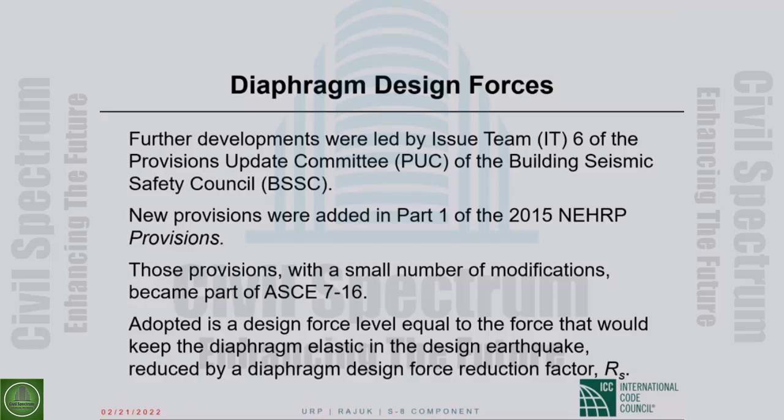Read that one more time. Can we consider slab on grade as a diaphragm if collector elements are inserted between slab on grade and column, but there is no connection between grade beams and slab on grade? Yeah. The answer to the first part is yes. The slab on grade can be a diaphragm if you choose to take lateral forces through the slab on grade.